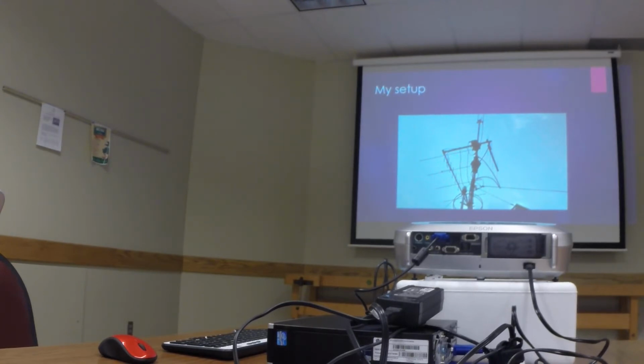They really recommend that you start at 5 watts and work your way up, which is probably right, but 5 is a bit of a challenge. That Yaesu rig will do 25, and I'll typically run about half of that, and I'm fine at about 12 watts. What modes? FM and upper sideband.